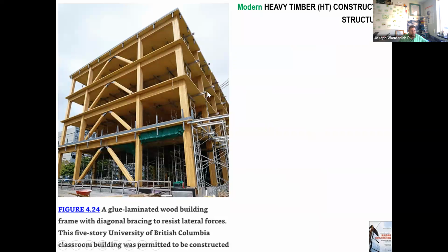And especially if you're going up like this and this, British Columbia, I'm not sure the seismic loads there, but this is your diagonal bracing. You have to do either moment connection or braced frame with your structural overall lateral loads. I mean, you do shear walls too, but to deal with lateral loads, especially in seismic areas, you either do this braced frame with these struts like this, or you make moment connections where you beef up the connections more, the moment connections, the torques, moments. It's more costly to do moment connection.